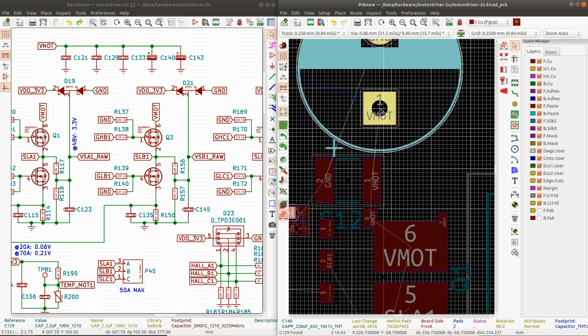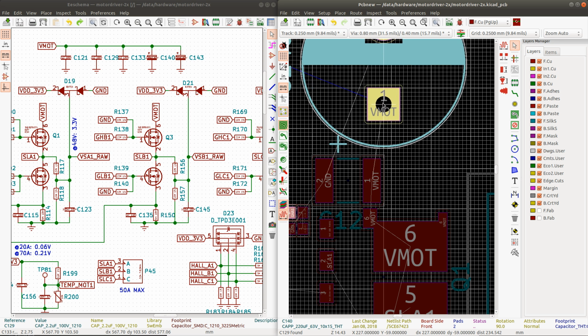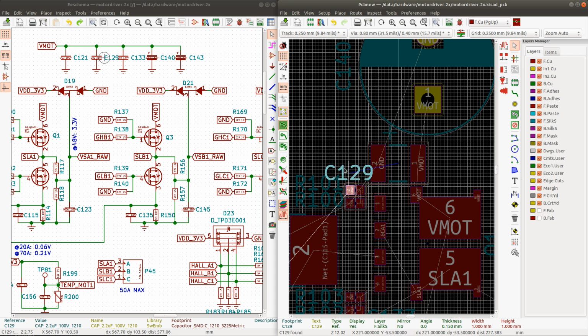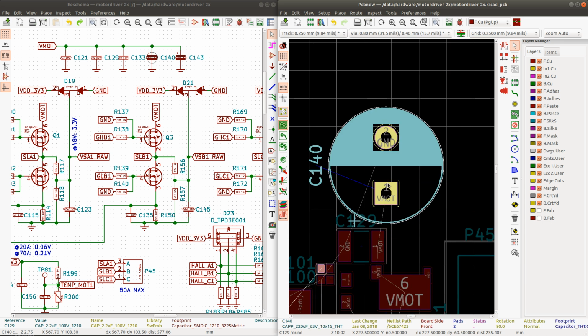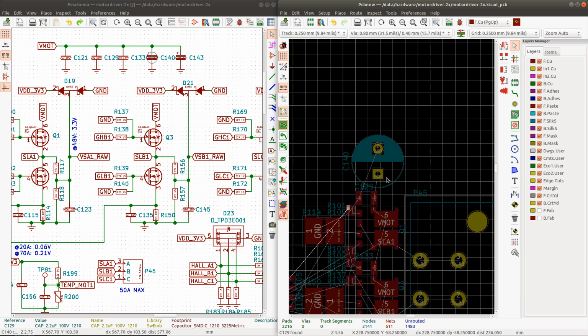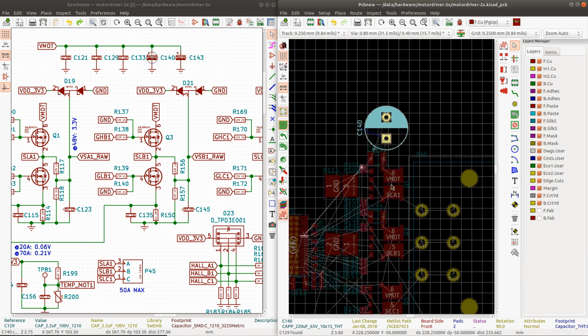So the purpose of the bypassing capacitors is to provide switching current. And that's true for every single bypass capacitor that you see on a circuit. They provide the store for the current for when you have to switch something. So if you have a load that you're switching, the bulk capacitors provide this extra current so that the current doesn't have to come from the power supply.